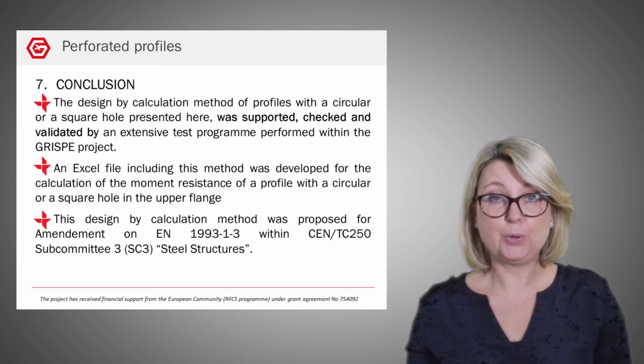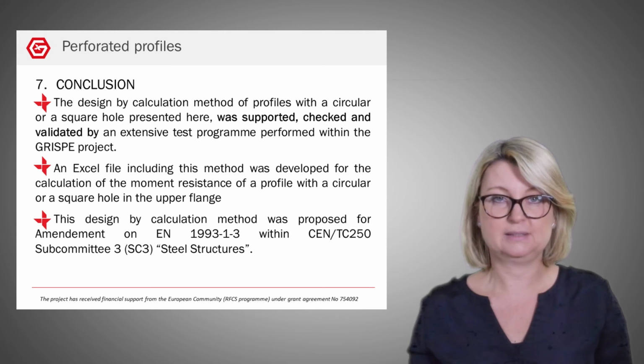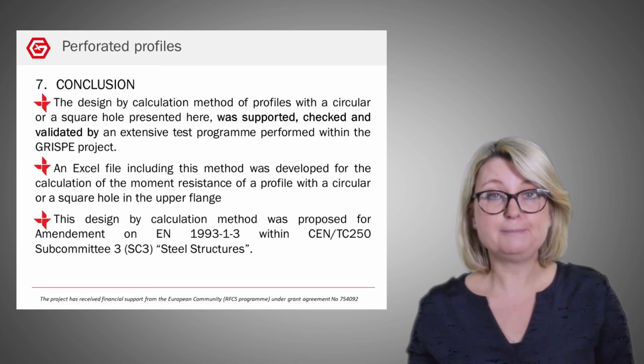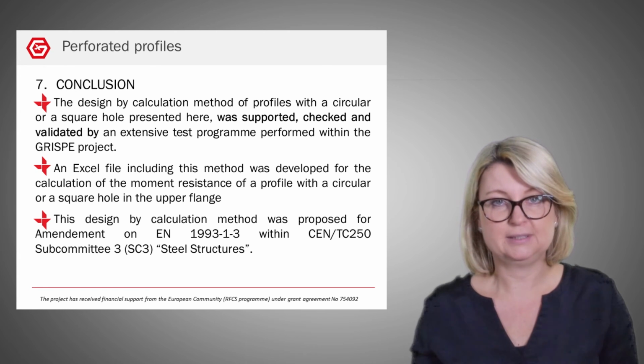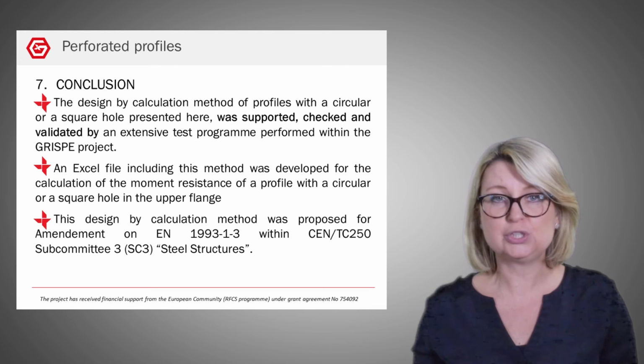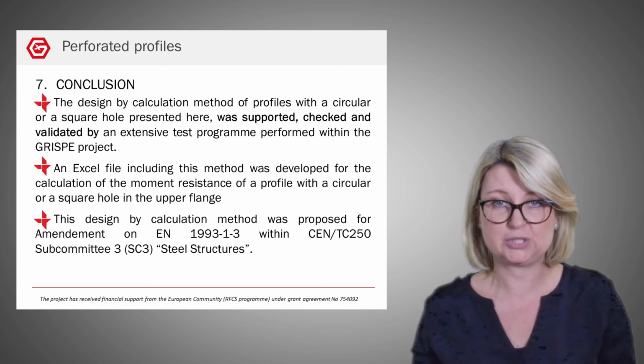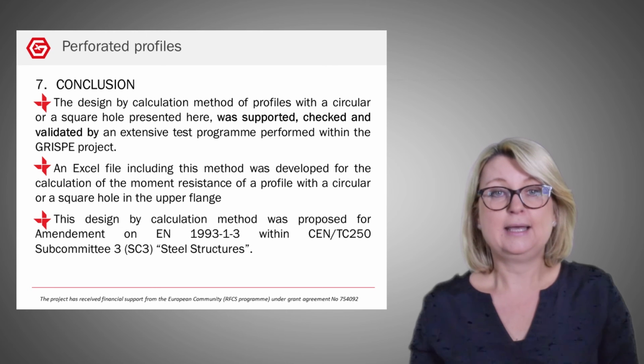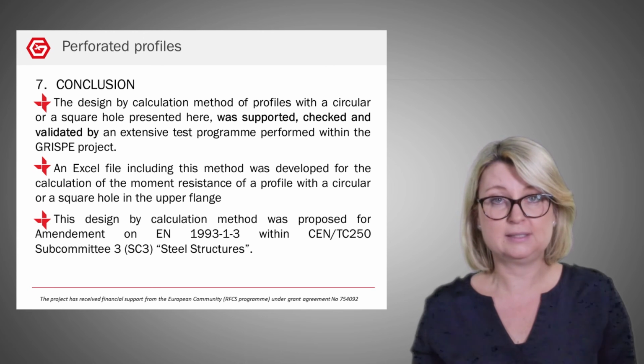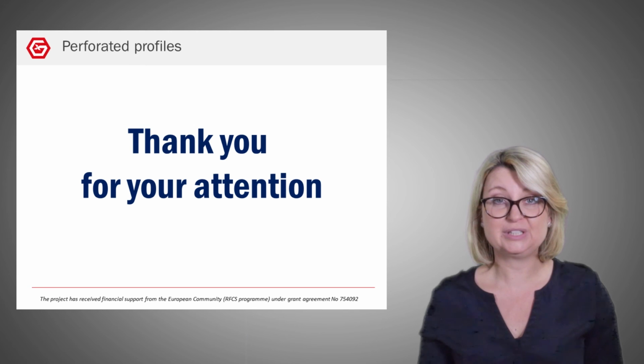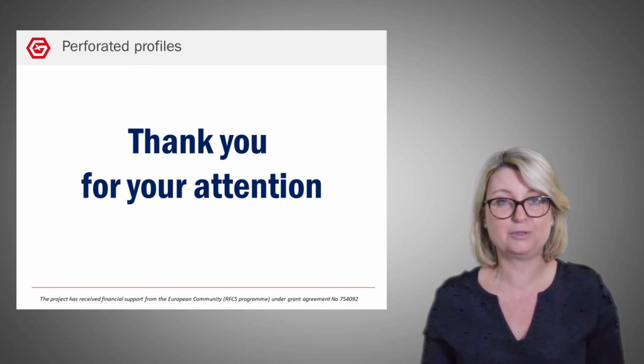To conclude, it is important to underline the following points. Firstly, this design by calculation method was supported, checked and validated by a huge testing program performed within the GRISP project. Secondly, an Excel file was implemented including this method in order to calculate the span moment resistance for a holed profile. Lastly, this method was proposed as an amendment on Eurocode 3 part 1-3. I hope I have contributed to making you more familiar with this methodology.